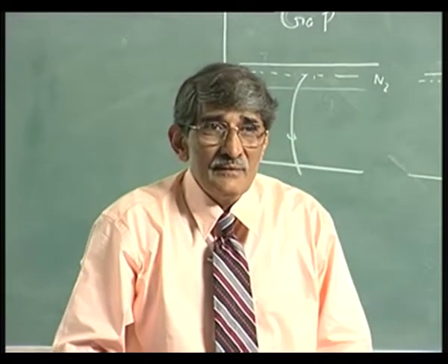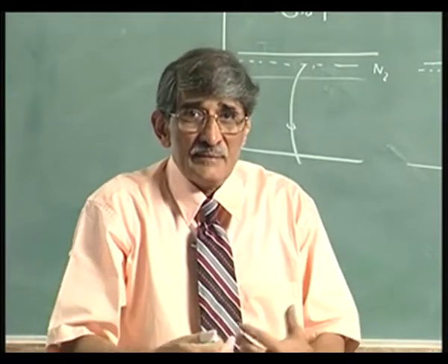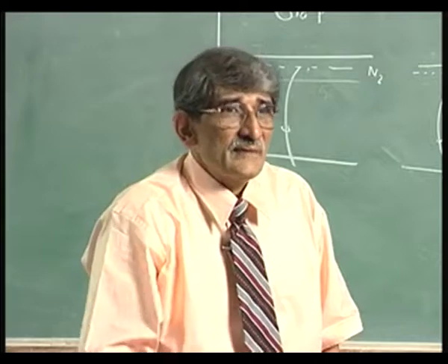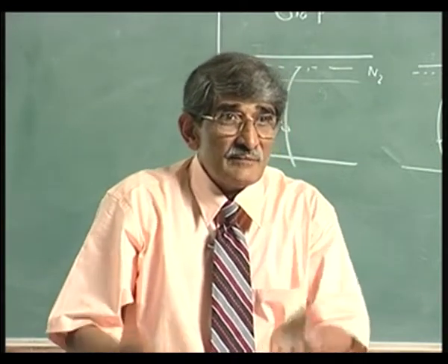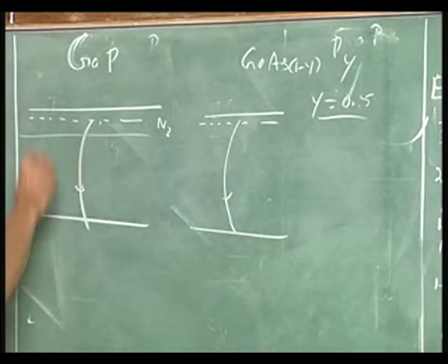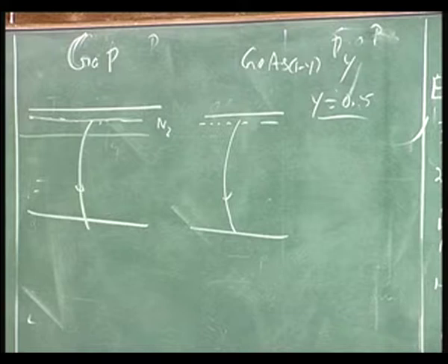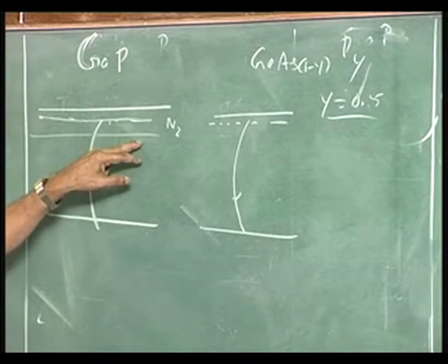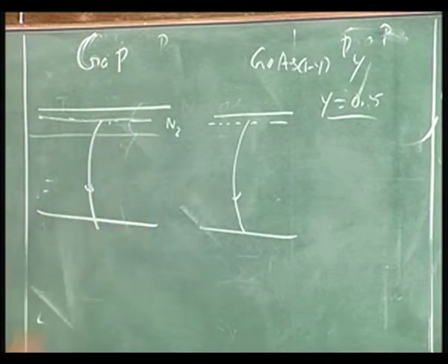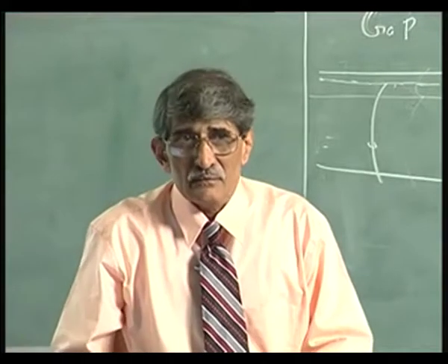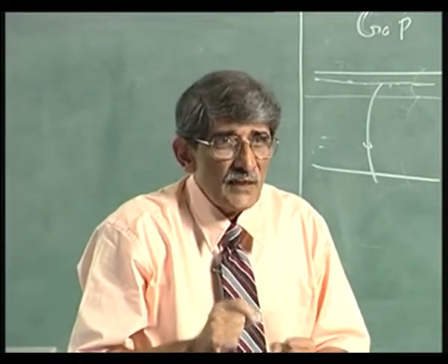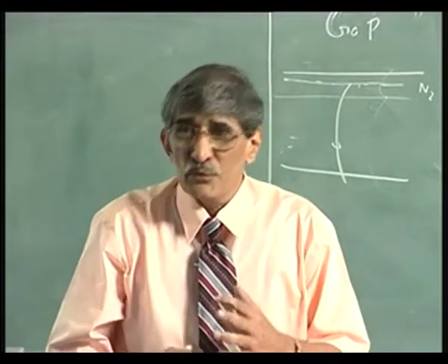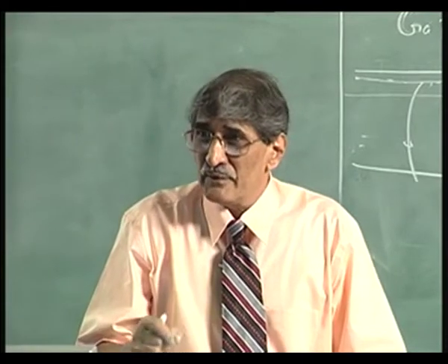But now, how much light is emitted for that particular wavelength depends upon how many impurities are present there. There may be unwanted impurities. Now, I have put two levels here. If you want green light, you must have only the nitrogen impurity, because of that wavelength. If I have one more impurity, what will happen? There will be some transition taken through this, so you will have unwanted emission. That is why when you make light emitting diodes, it is important that you have a pure material. The growth must be really pure, and you must be able to introduce only the impurity which you want to introduce.